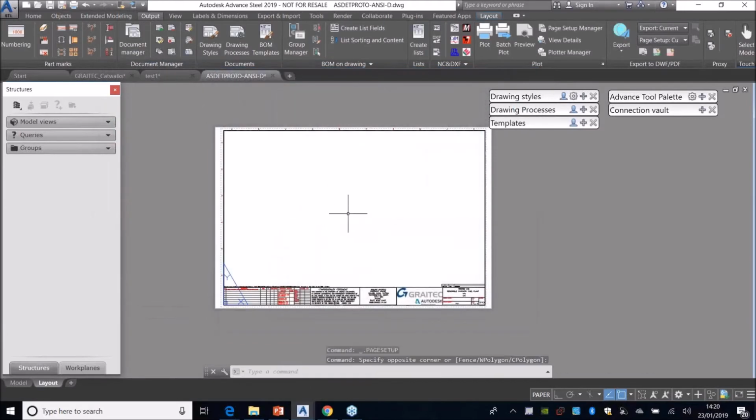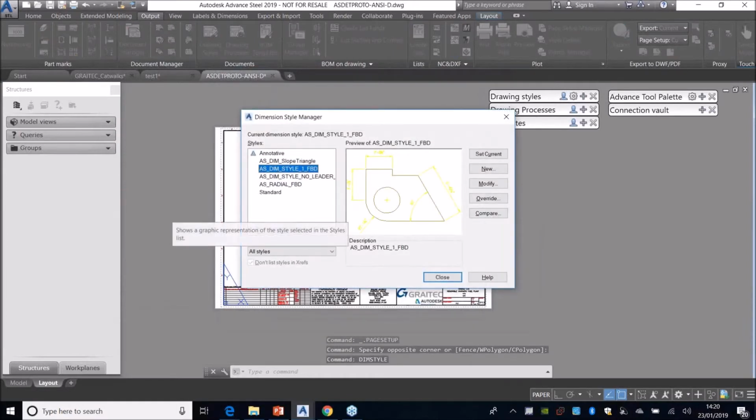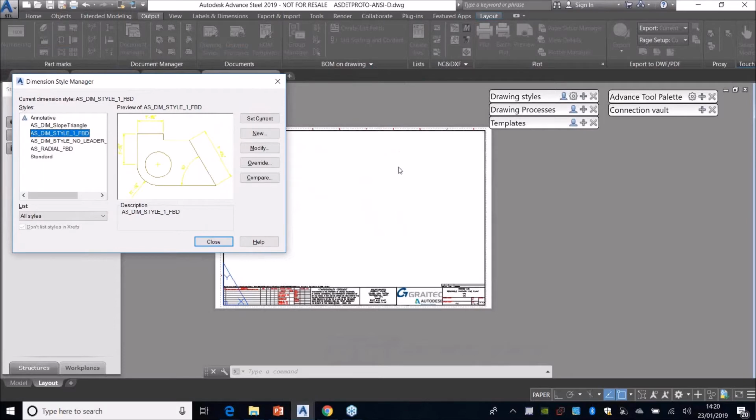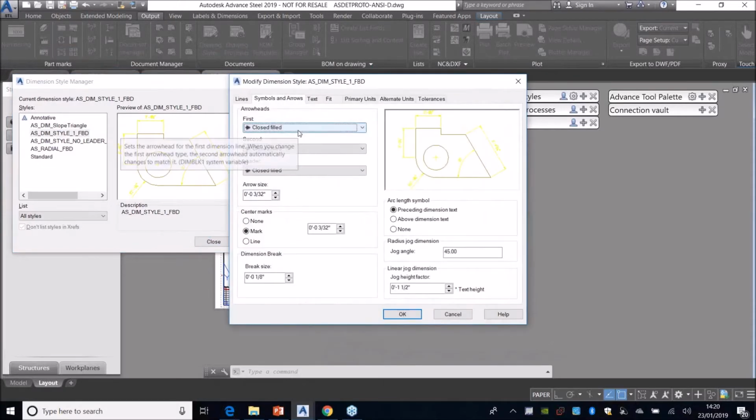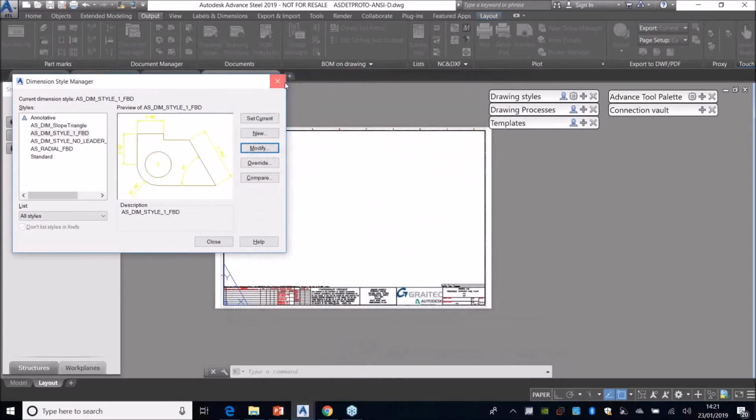A couple of other things. Your dim styles. So your dim styles, you can look at this in two different ways. Okay, you can have a different dim style in each individual prototype file, which makes this very easy to manage in terms of colors, display types, so on and so forth. Okay, so if you have multiple customers, each one has their own specific settings here in the defaults, and I mean in the prototype file, and that's again easy to manage. You don't have to think about going and modifying your defaults back and forth per project that you're working on.